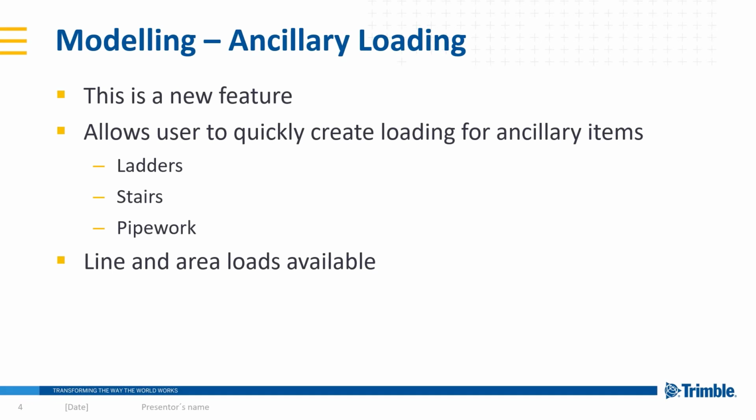With ancillary loading, this is a new feature released as part of the Tekla Structural Designer Service Pack 4 updates. This feature allows you to create loading for ancillary items such as ladders with and without cages, stairs, pipework, walkways, etc. These loads can either be set as line or area loads. We'll now look at how to model these in Tekla Structural Designer.